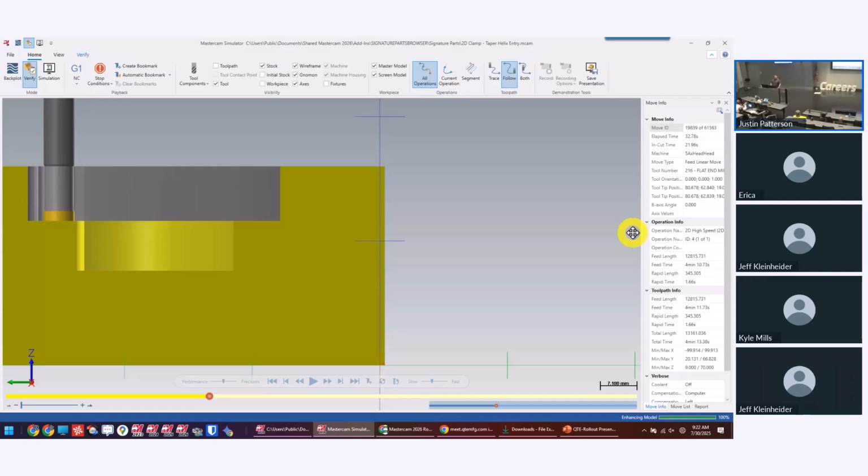Okay, test this. For your hard materials, it's all short chipping. So that's not as difficult, but in your long chipping materials, that taper is going to really reduce the chip length, especially when you're down in a cavity like that. Plus it helps get those chips out of there. It's just a win-win altogether.